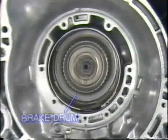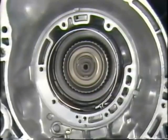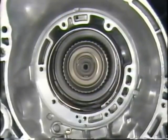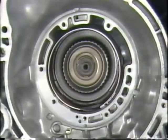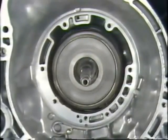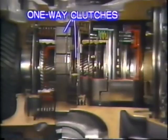This is a band-type brake. In a band-type brake, the brake band squeezes the brake drum, which is connected to a member of the planetary gear set, preventing the member from rotating. One other type of brake consists of a one-way clutch. A one-way clutch locks a gear or carrier so that it revolves in only one direction.